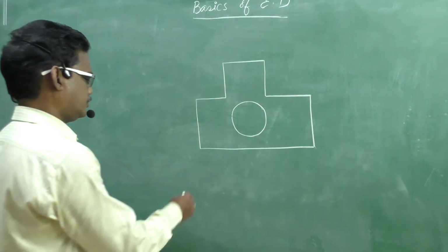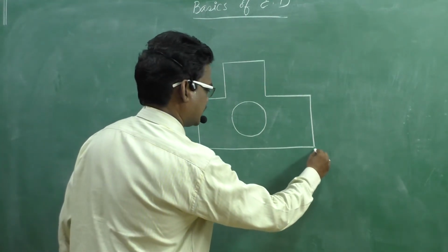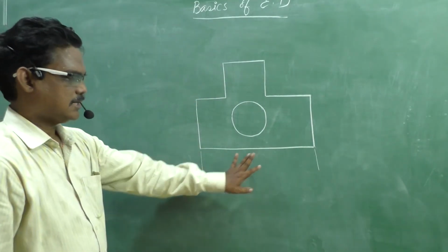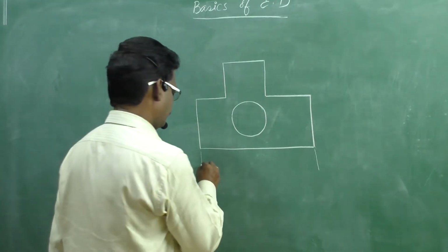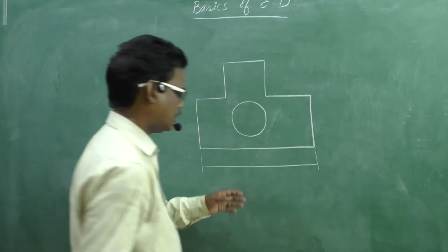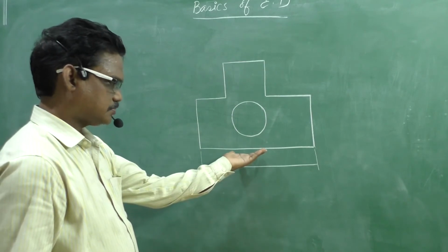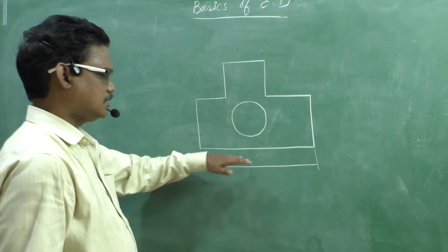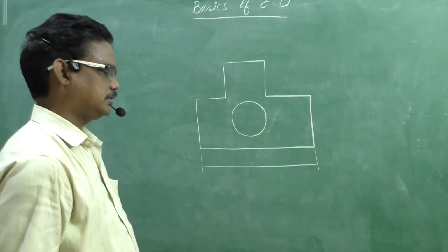Now these are called extension lines. These extension lines must be thin lines, and let this line length be 100 mm. Therefore, draw a line parallel to this edge. If we measure this edge parallel to that, it will be 100 mm. That is the reason, with the help of the mini drafter, we need to draw a thin line.